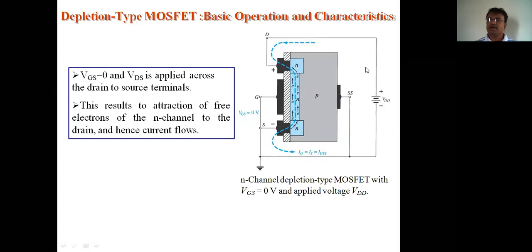So electron flow is in this direction. Just see the cursor in which direction it is moving. Here it is shown, in the black arrowheads. Electrons always move from source to the drain. Then also you know that the conventional current is just opposite to the flow of electron current. So the electrons are moving from source to drain. The drain current flows from drain to the source, ID. ID is the drain current. Drain current is just opposite to the flow of electrons.